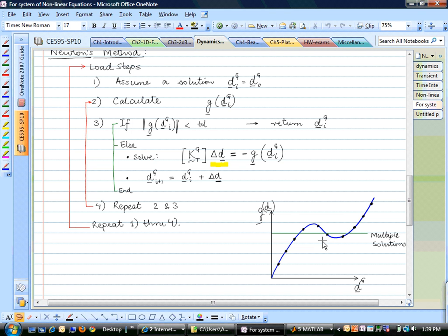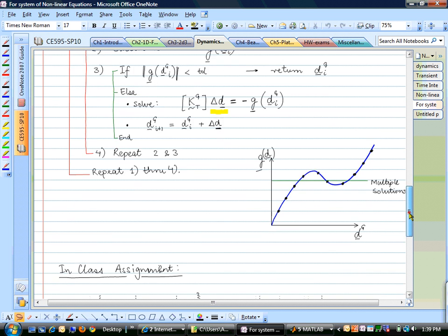Also, those of you who are using the nonlinear Abaqus methods, if your problem has some kind of an instability, meaning that if you reach a maximum point and then you start to decrease the load, in that case it is better to use the static Riks method. The Riks method always makes these types of cuts along the equilibrium path. So the Riks method is used whenever your problem has some kinds of instabilities.